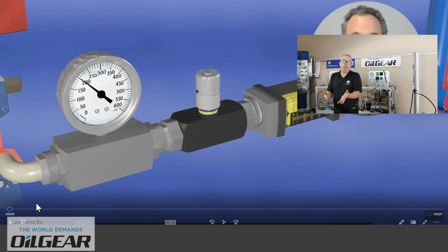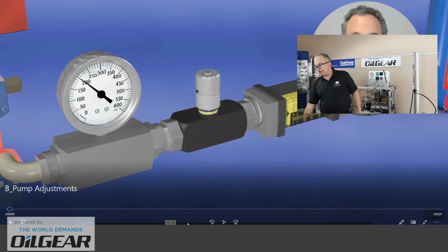Enter the piston pump, which allows us to have a controller for that swash plate and say, hey, if we get to the point where the system pressure is too high, perhaps we could just reduce the flow from the pump to near zero and then hold the outlet pressure with just a tiny tip back on stroke of that swash plate, and be ready for a time when the directional valves open once again, when the hydraulic cylinder isn't overloaded, and then the pump could come back on stroke automatically. And that's one of the jobs that is covered off by the pump's pressure compensator.